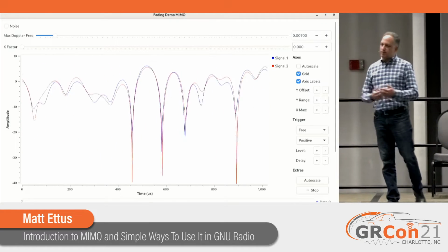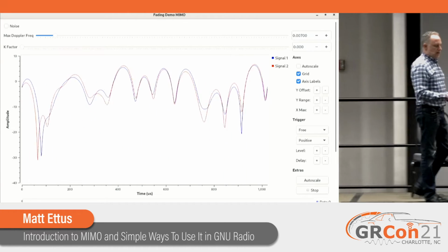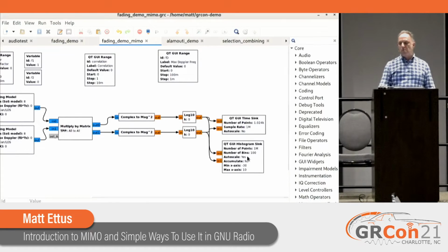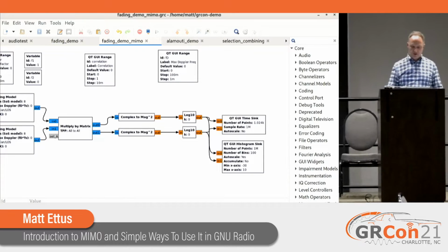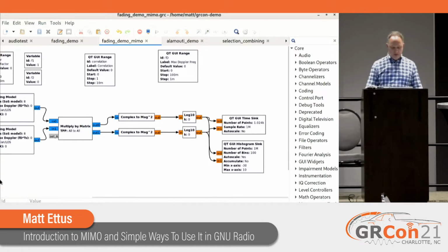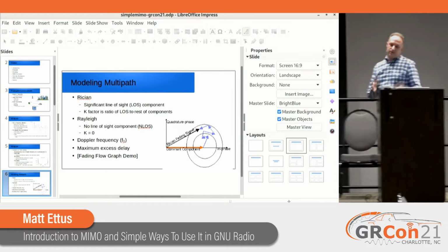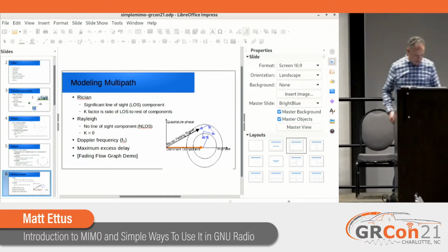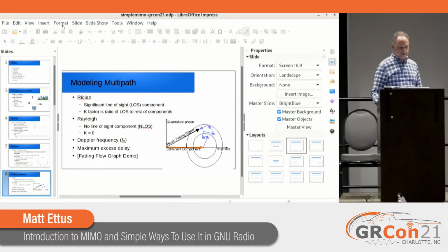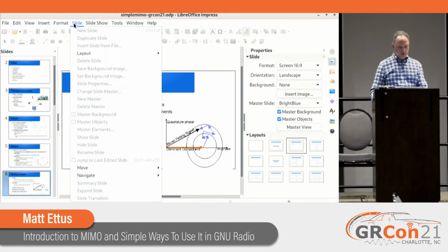And in terms of using MIMO techniques, the lower the correlation, the better, because you get more diversity out of it. But in general, you can get useful results down to moderate correlations of 0.5 or so. Now, if you do have perfect correlation, as if it was free space or some other situation where you happen to have the antennas too close to each other, then you won't get the same level of improvement from MIMO, but you may still.